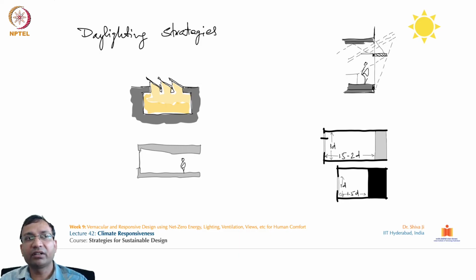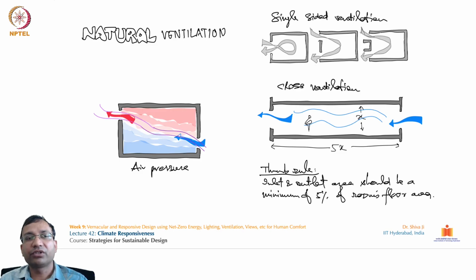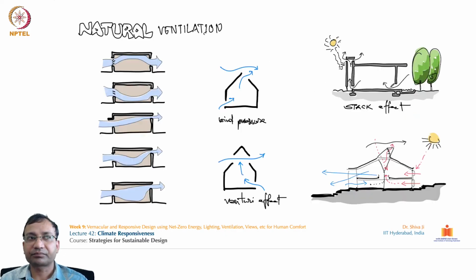Further, promoting natural ventilation, we have some solutions over here, like how we can devise openings, how we can propose openings in the building structure to control the wind, or to control the flow of the wind inside our structures. The strategic location of the inlet and outlet points also should be decided, because if you want to have a scouring effect of wind inside the space, to have the maximum effect, maybe the location of these entry and exit points could be at the diagonal level. Okay, so that will maximize the overall efficiency for the cooling effect.